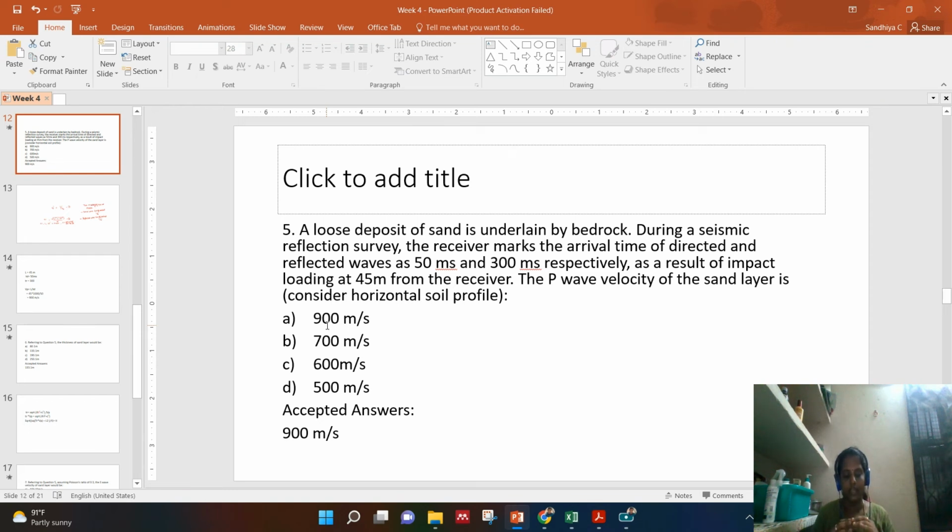So the lower layer is underlying higher resistivity. So you have the low layer below, the higher layer above. That means, instead of high and low, we keep that as rock and soil. Soil is low resistivity, and rock is high resistivity. So in your first option, rock is lying below soil, and in the second option, soil is lying below rock. It has a difference. In soil itself, sand has different resistivity than clay. Okay, so just to have an idea, we know that rock is